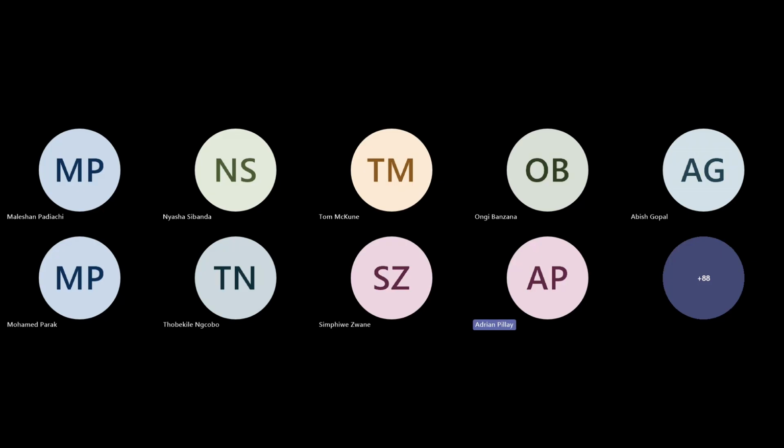Yes, Tom and Gofi. So the HDPE pipe was fully encased in concrete. Hence, it prevented the movement of the pipe, and the subsequent stresses from this restraint were accommodated for in the designs of the deck. Notwithstanding that, the pipes were free at the bridge abutments at the ends of the deck.